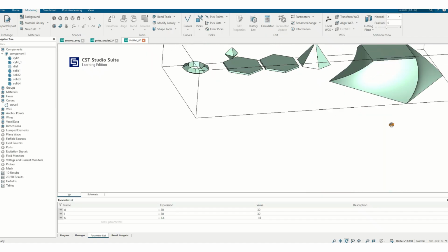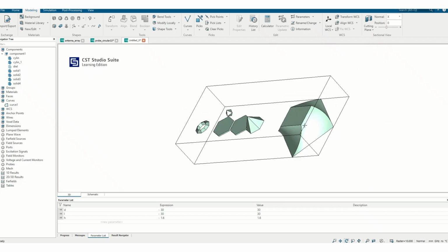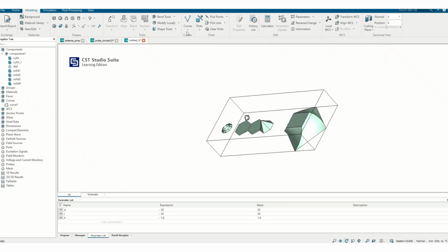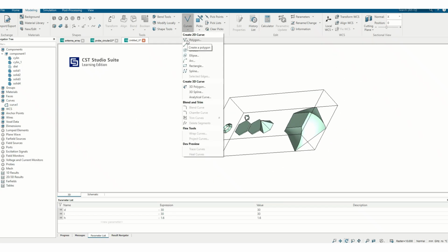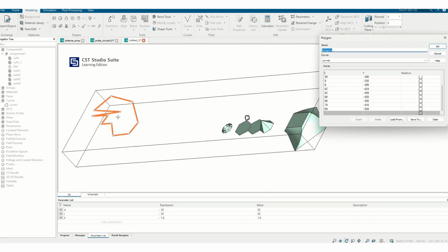So this is how you can create different types of structures if you want to create 3D geometries. And if you have to create any polygons which are not as per any standard geometries, you can use this polygon, and based on that you can create structures like this, and you can see how these x and y coordinates are formed.